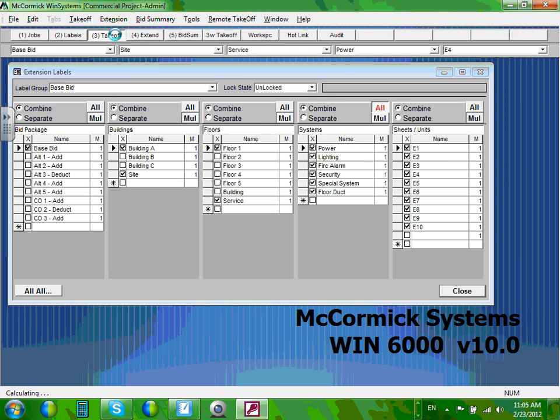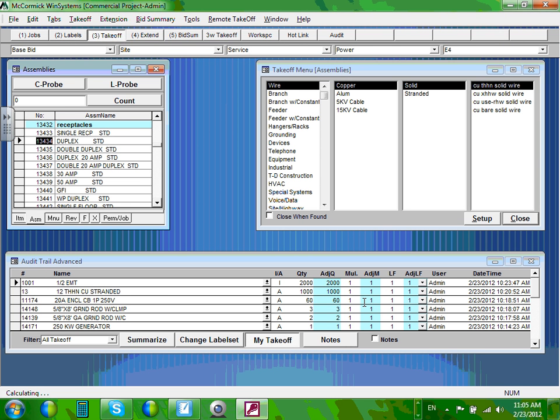And we said, and William, my friend, we said we spend a lot of time in the takeoff here. The key point for you guys being beginners is understanding the menu and picking up the stuff from the menu as an assembly first, dump it into here, and add the count or the length and drop it down into the audit trail, right? So really the amount of time is going to be spent on trying to find what you're looking for.